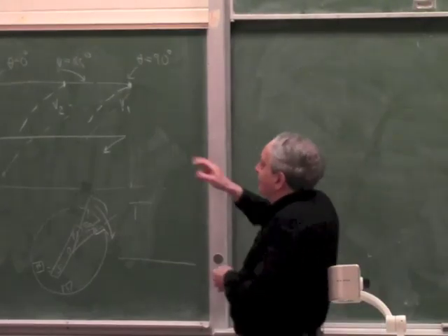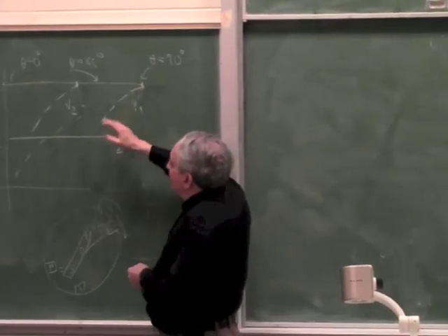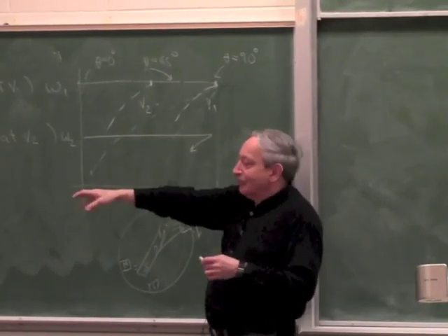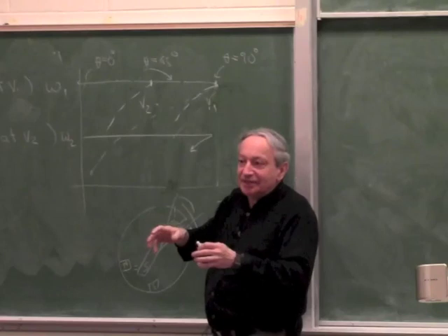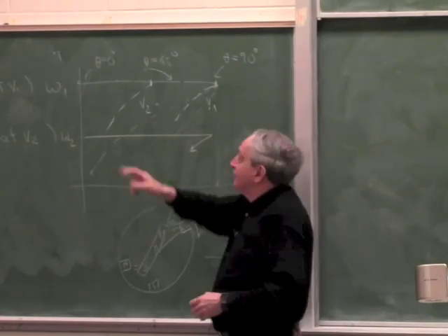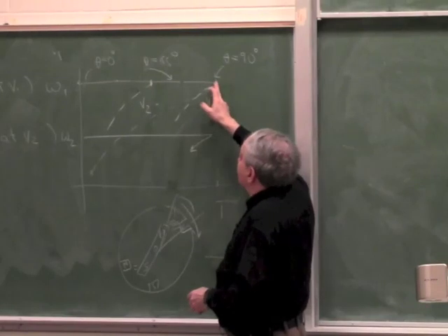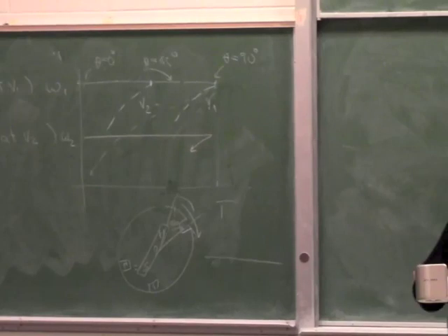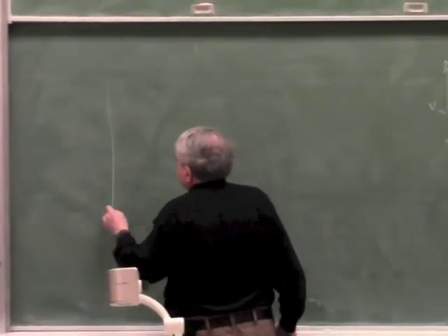Because the moment you start, omega ramps up instantly, because when you start the motor from the power line, you apply the full omega instantly. So the moment you apply the full omega instantly, it already wants to turn at full speed. Because of the inertia, it's already at this point and collapses. Good. So now let's talk about induction motor.